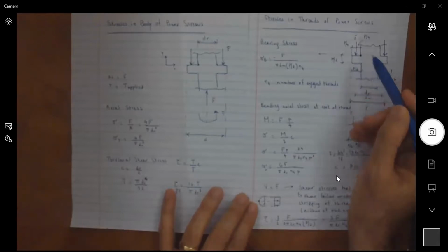So we are looking at a stress at a point, really combined stresses. So the best way to understand that is to look at a stress block and look at all the different effects so that we can evaluate whether failure is going to occur or not. So I want to combine the sigma y, this tau yz, and this bending stress that we called sigma x. So that's what I'm going to be doing next.